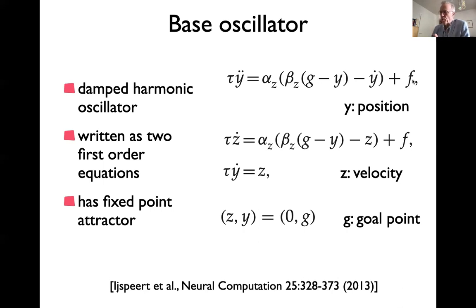The harmonic movement will lag behind the forcing function and will smooth it, with a characteristic frequency window that depends here on the stiffness and the damping. They're combined in some funny way. So alpha times beta would be the stiffness, and alpha alone is the damping. And it's written so that you can express critical damping when these two would have the same units and the same value if expressed in time units.